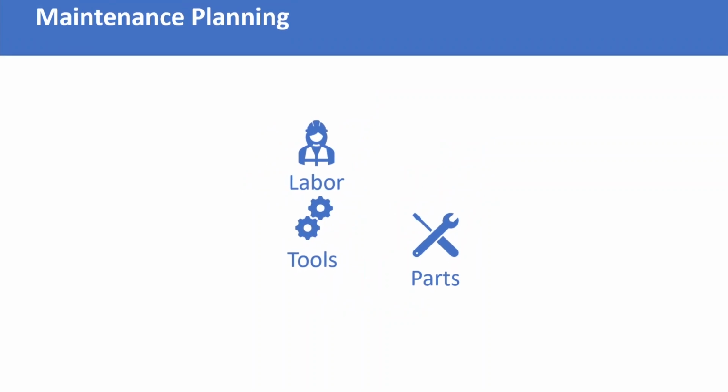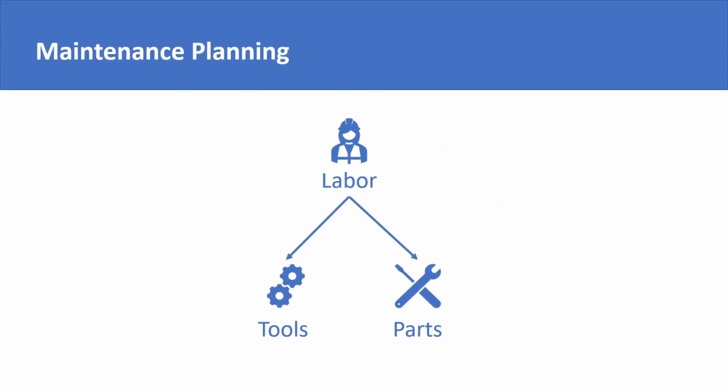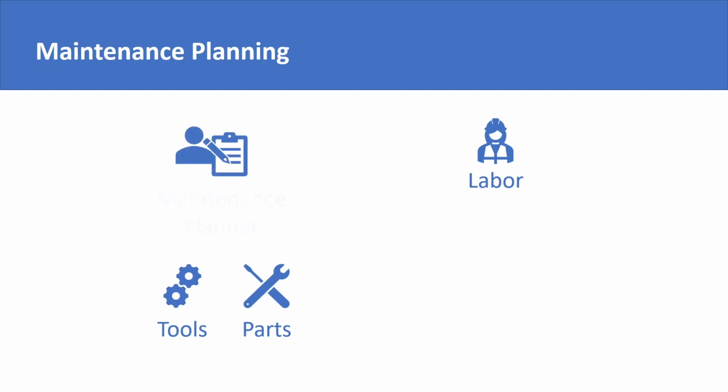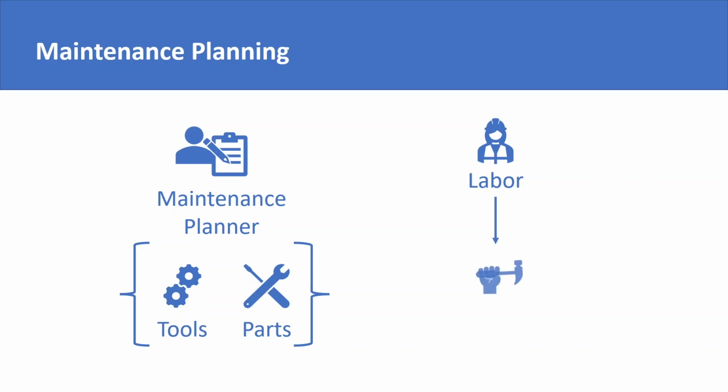The basic concept of having maintenance planning is to save time of technicians in getting parts and tools. Maintenance planners plan the job for them and lay down all the requirements of tools and parts. This allows the technician to get going with work without spending time on figuring out all the tools and parts needed for the job. Here, it is important to discuss a very important statistic in maintenance work management. It is called wrench time.